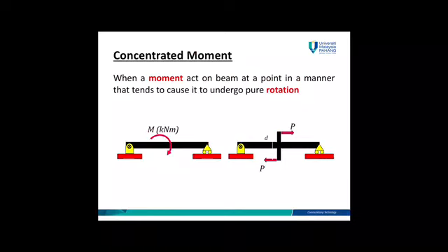We also have a concentrated moment, which is an applied moment. It tends to cause a rotation to the beam. So in your analysis of beams, you need to include the applied moment in your analysis, or else your maximum moment and also maximum shear will be wrong.